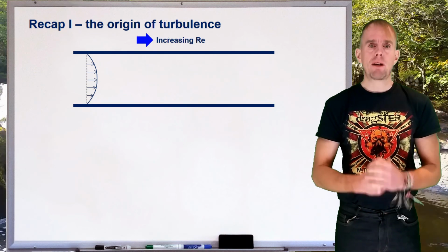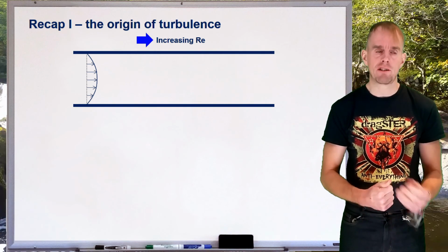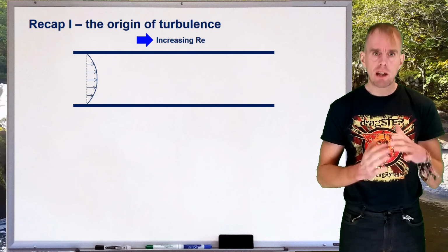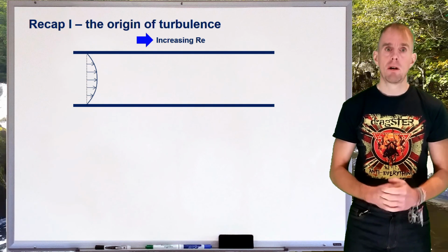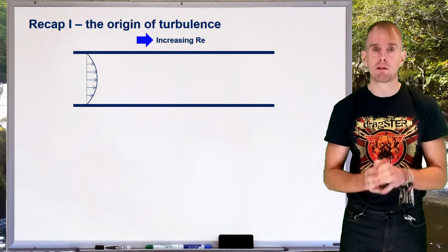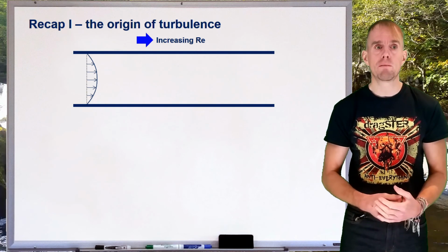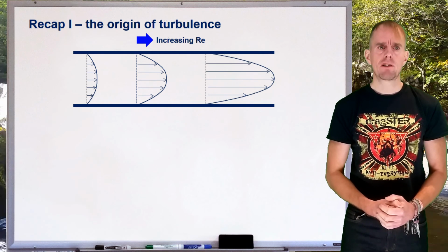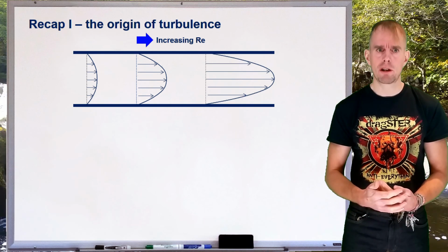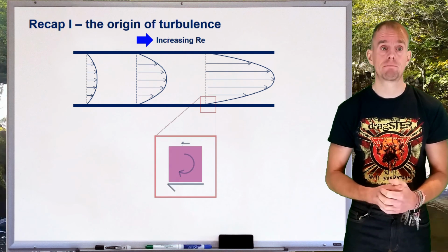Now, that's for laminar flow. Simple laminar flow in shear will have rotation as an inherent property. So let's keep our shear flow and gradually increase the Reynolds number and see what happens. If we keep our flow geometry and material properties the same, then increasing our Reynolds number means increasing our flow velocity, which means we start to stretch our velocity field like so. As our velocity field stretches, we can perhaps see that the shear stress imbalance on our element of fluid gets greater and greater.